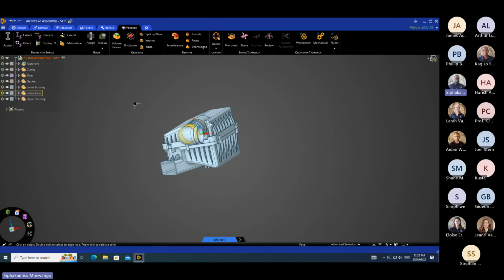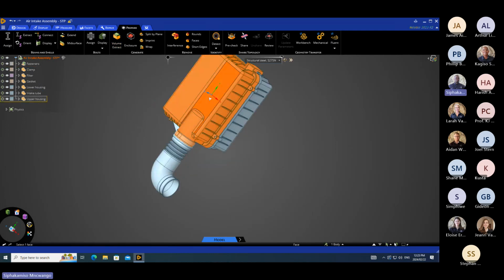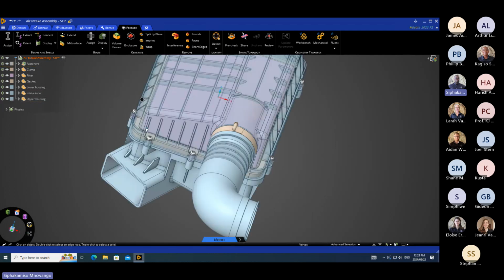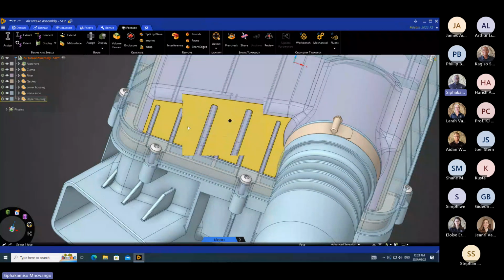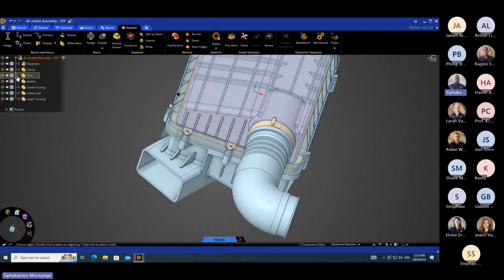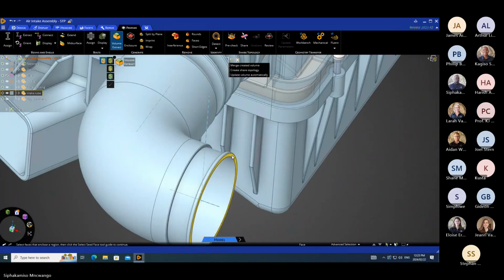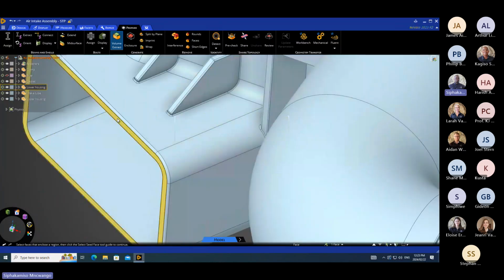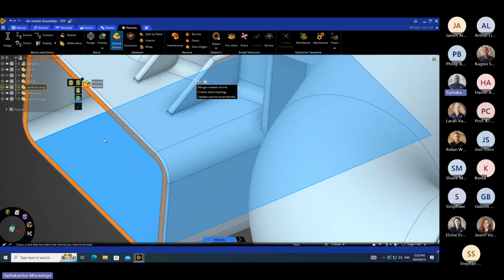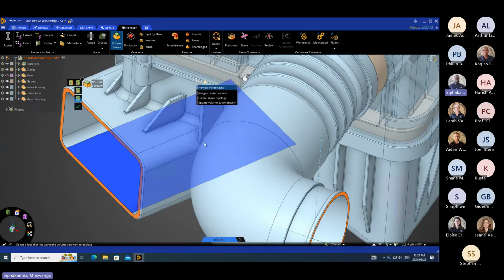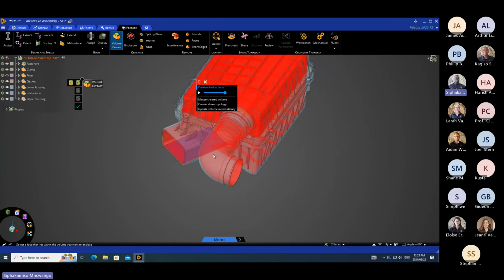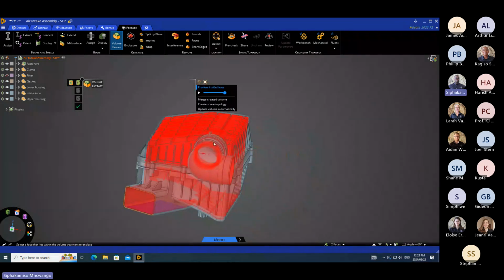That is caused because if we go here and we triple click here and we make this transparent, we can see that there is a pink filter in there. So the volume that's being extracted is being blocked by that. So what we can do is quickly hide the filter and just reattempt to extract our volume again. Inlet, exit, and then seed face. And quick preview. All right, now we see we have our volume that is closed within our geometry, and now we can capture that volume.